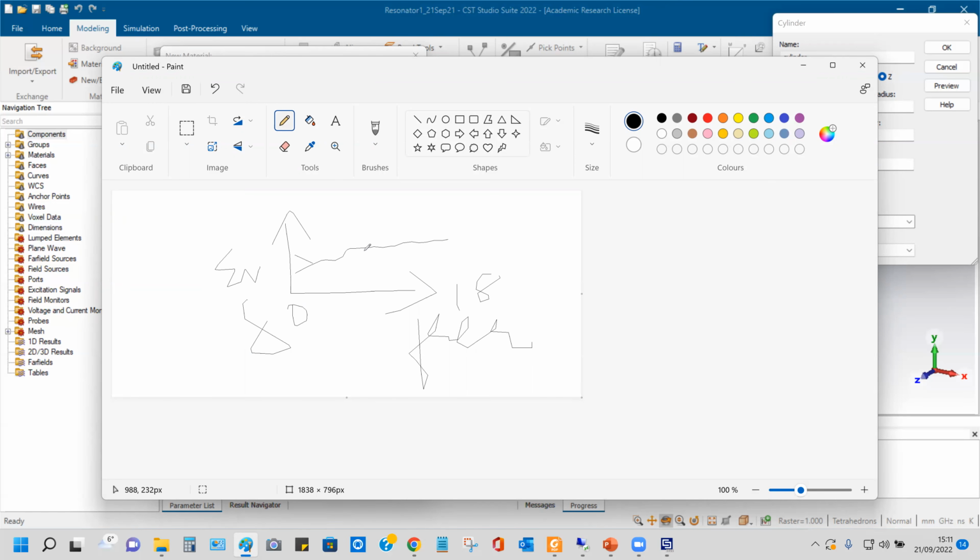But they will represent it in the data sheet as, for example, 2.2 at 10 gig. So 2.2 is the value applicable only for that frequency. There will be a variation, plus or minus something. Some data sheets also give the tolerance, plus or minus 0.2, 0.5, like that. Which means this dielectric constant may, for example, come from 1.8 to 2.8. Plus or minus 0.5 means 1.7 to 2.7.